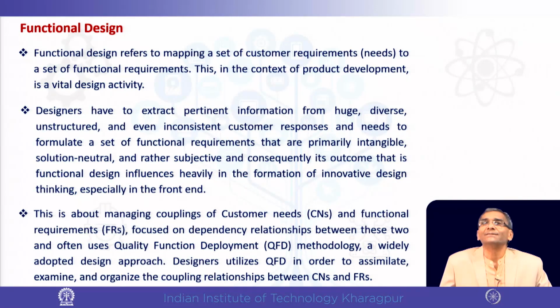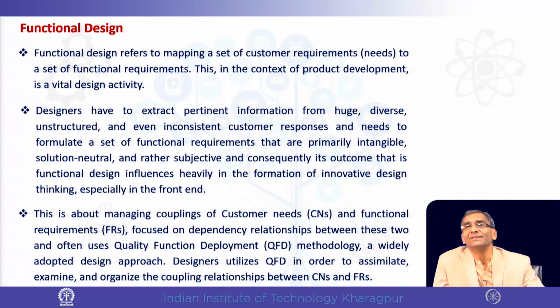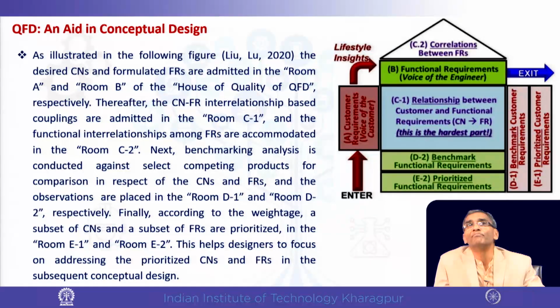And for this, a very handy tool is QFD, or quality function deployment, that brings in these two, the CNs and FRs, in a matrix form, which is very easy to comprehend. It is also often called a house of quality, or voice of customer, because the voice of customer is being captured through this model.